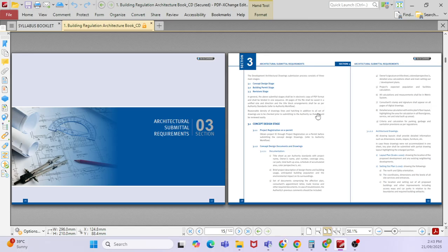Sometimes your design may not be feasible or workable to construct. Maybe whatever you design is not feasible for construction sometimes. So you will get a lot of comments from the contractor. Then again you will incorporate all the authority comments and contractor comments, and you will generate a final design which is called IFC.